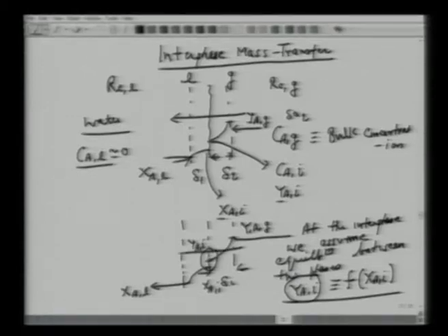However, there is a transport, there is a diffusion, at Na. So sulfur dioxide diffuses from the gas side to the liquid phase because of this concentration gradient in the gas phase and within the liquid phase. At the interface, however, there is an equilibrium, YAI as a function of some XAI.